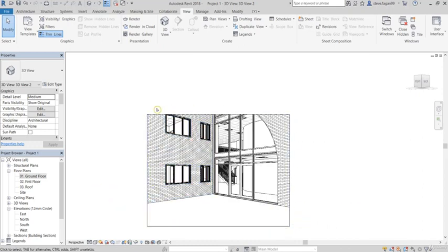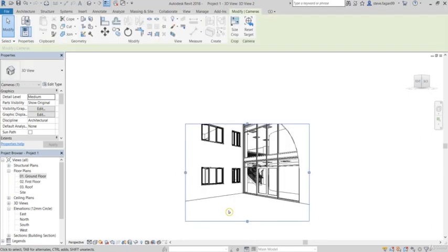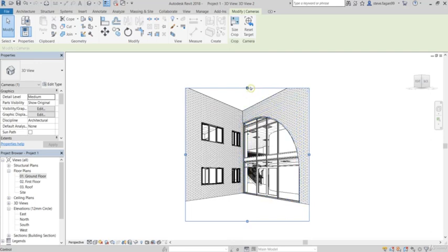So we have a rectangular box around the image. That's just a crop view. So if we wanted to change or resize our crop, we'll just have to select it to highlight it, and there's our grip, so we can just pull and drag it up.